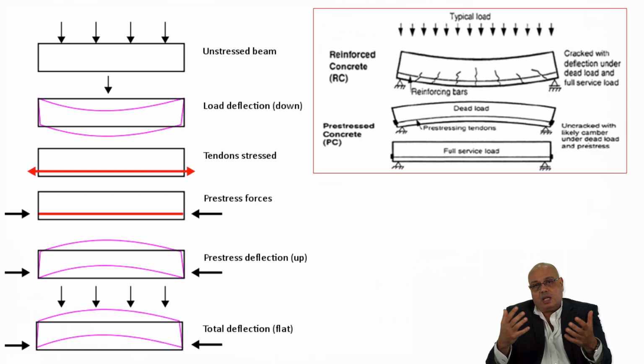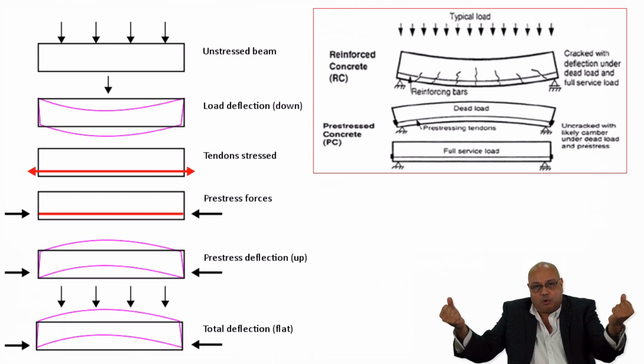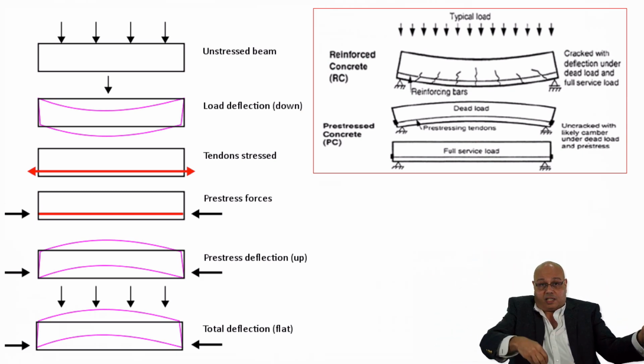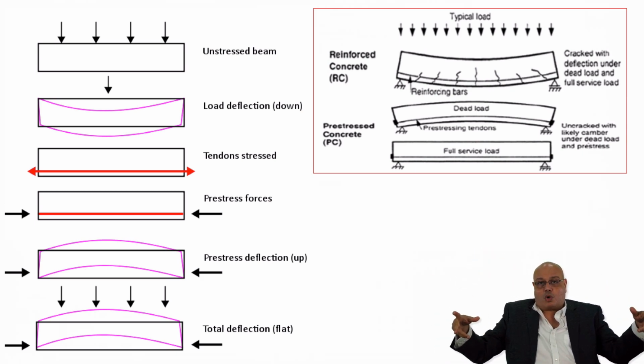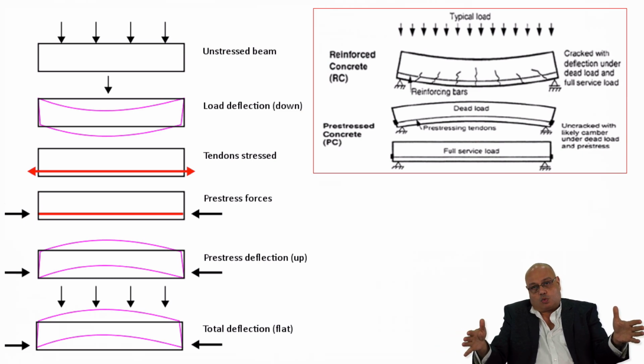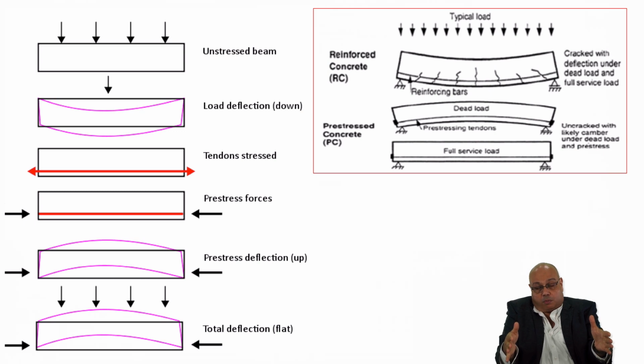It's primarily about when you pour the concrete, meaning you stretch the cable first. And in the form, you pour the concrete. And once the concrete hardens, you cut the ends of the pre-stressing strands so that it will compress the beam and it will be pre-stressed.